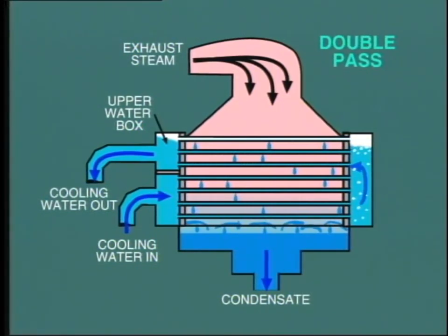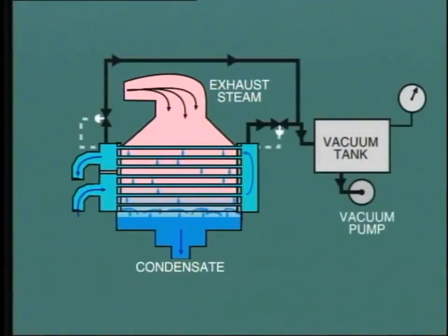The result of this reduction in heat exchange will be that the condenser is less effective and the turbine back pressure increases. The siphon connection prevents this from happening by drawing off the air at the top of the water box and piping this into a vacuum tank. The vacuum in the tank is maintained at about 25 inches of mercury by small vacuum pumps that are intermittently operated.